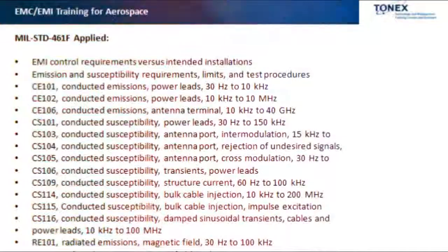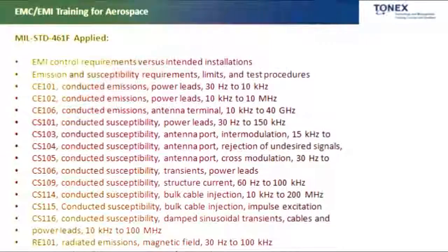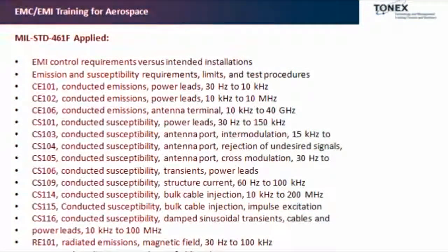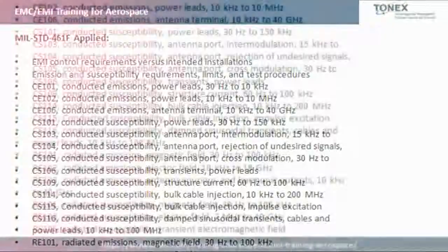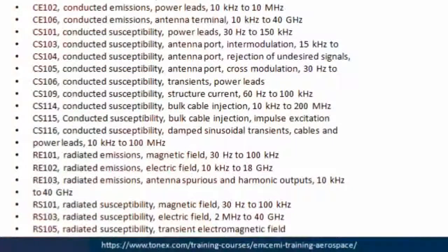CS115, conducted susceptibility, bulk cable injection, impulse excitation. CS116, conducted susceptibility, damped sinusoidal transients, cables and power leads, 10 kHz to 100 MHz. RE101, radiated emissions, magnetic field, 30 Hz to 100 kHz. RE102, radiated emissions, electric field, 10 kHz to 18 GHz.